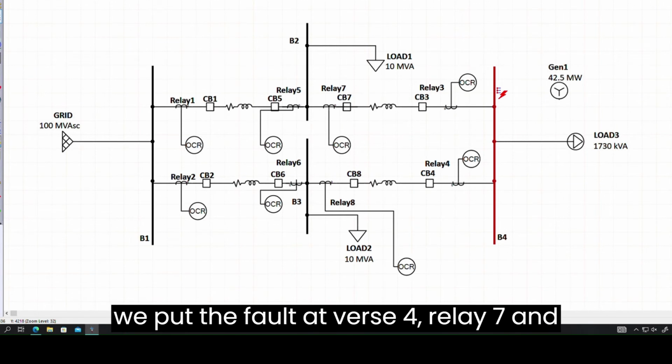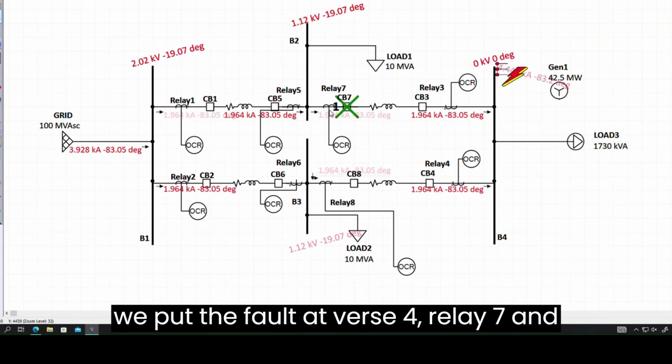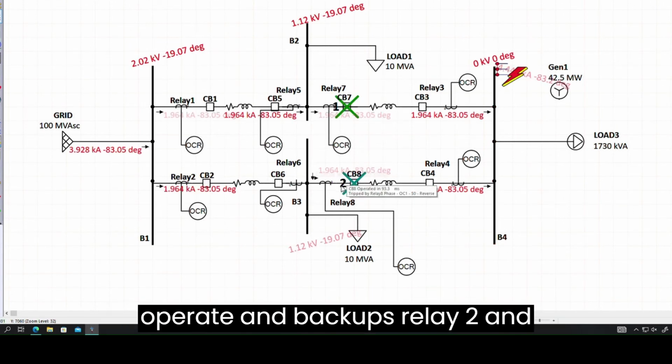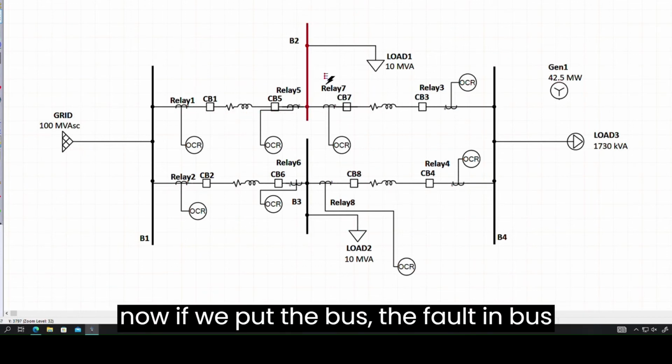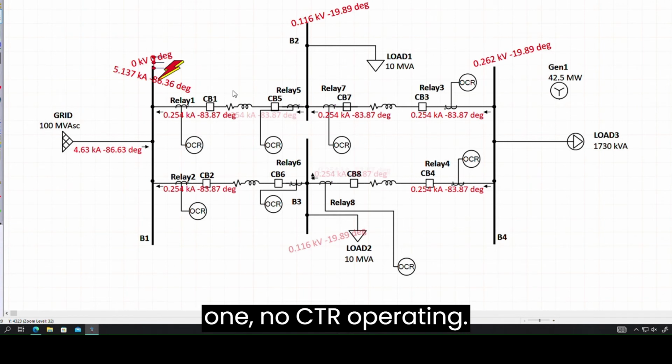And then if we put the fault at bus 4, relay 7 and relay 8 are going to be the first to operate, and as backups, relay 2 and supposedly relay 1 should operate. And now if we put the fault in bus 1, no CTs are operating.